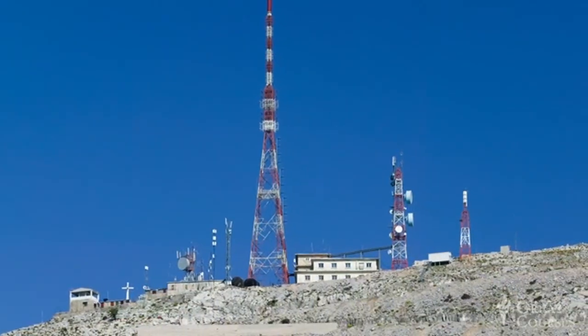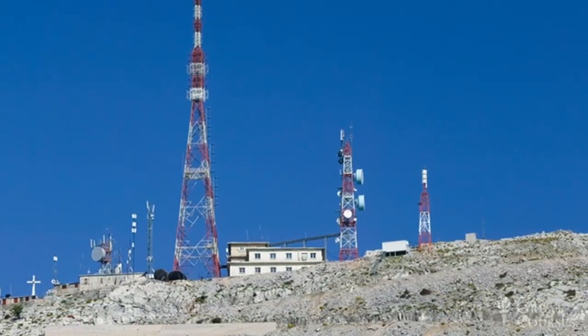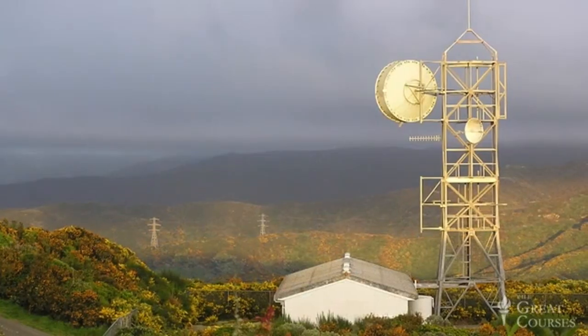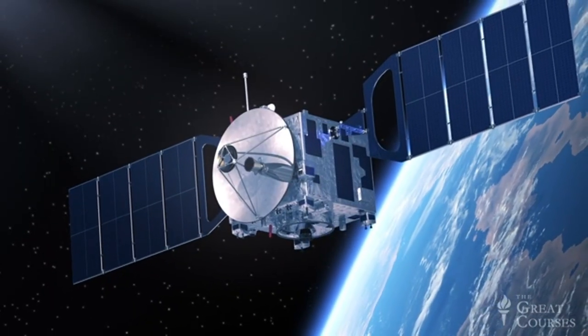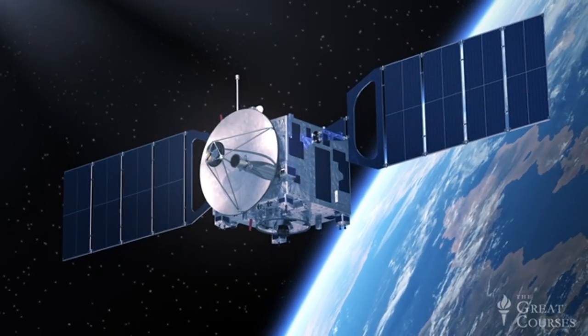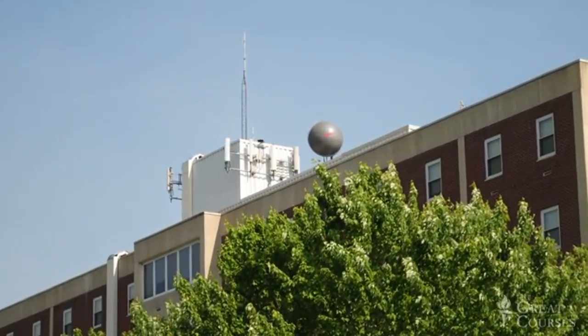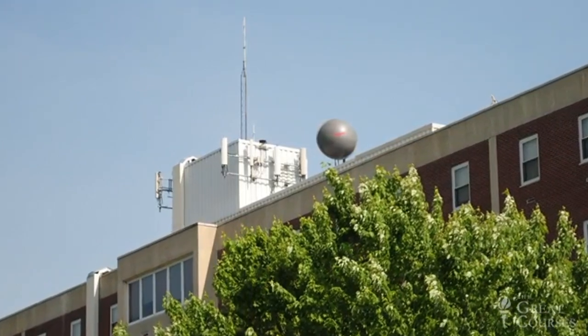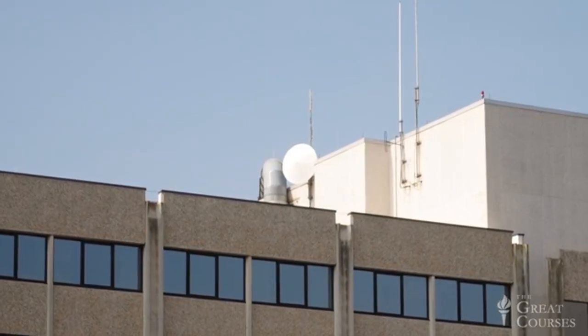Now today, microwave trunks in the PSTN have mostly been replaced by fiber optic cable. Yet microwave remains quite valuable for situations where stringing cable can be problematic, for crossing deserts or mountainous regions, and for connections to remote locations like islands. The microwave band is also used for satellite communications, an application for which cables of any kind aren't particularly helpful. And today, this technology is finding all sorts of new applications in private commercial point-to-point communications over relatively short distances, as illustrated by this directional antenna on this hospital roof.